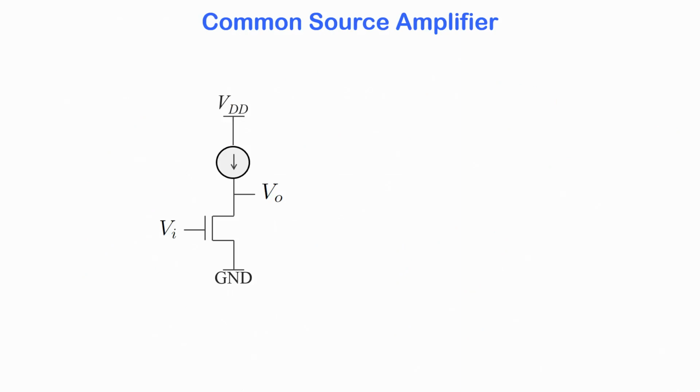So, the answer to high gain is to find a device that will give us a current source, so that no matter what the fluctuation across this device, the current is always a constant, which means the small signal output impedance is close to infinite. So, that is the device we want. It will give you a finite voltage drop, but infinite output impedance. So, that is the magical device we are looking for.